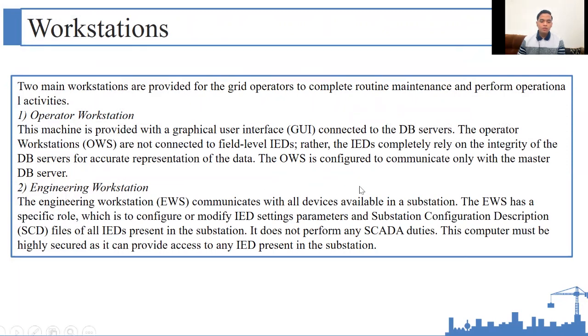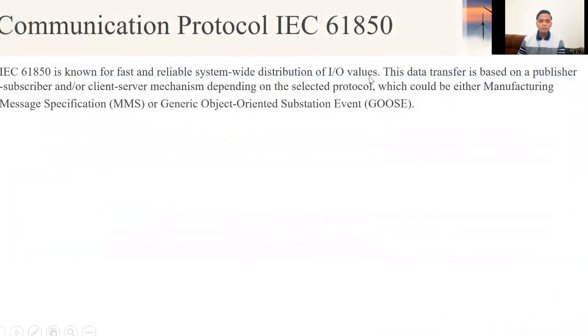Number two, the engineering workstation. The engineering workstation communicates with all devices available in a substation. Its specific role is to configure or modify IED setting parameters and substation configuration description files of all IEDs present in the substation. It does not perform any SCADA duties. This computer must be highly secured as it can provide access to any IED present in the substation.